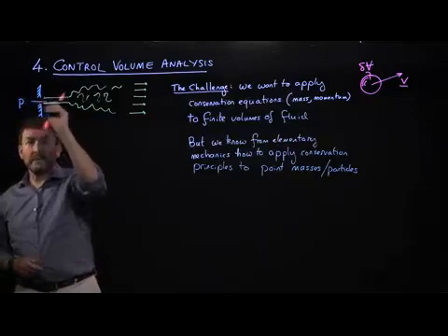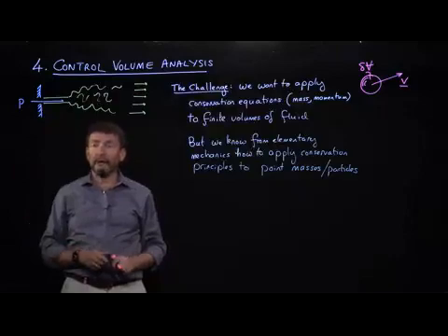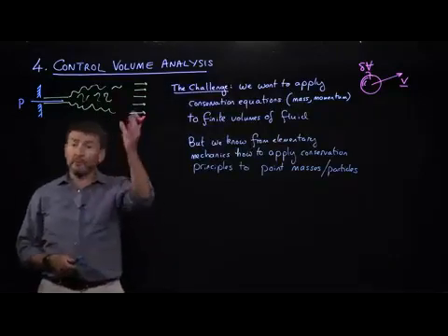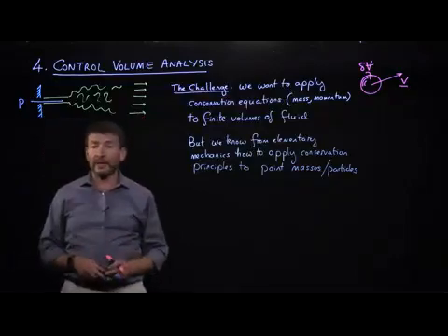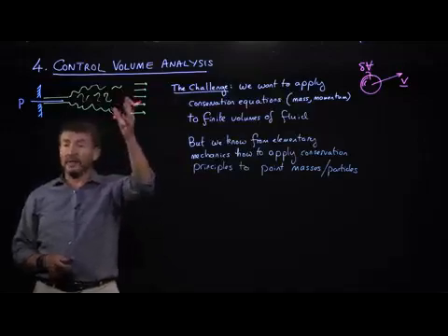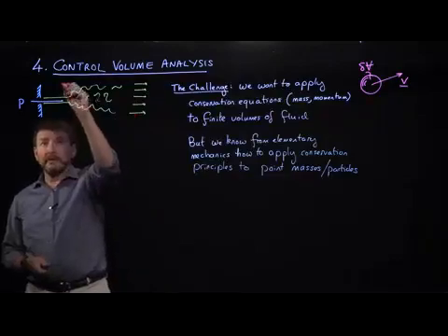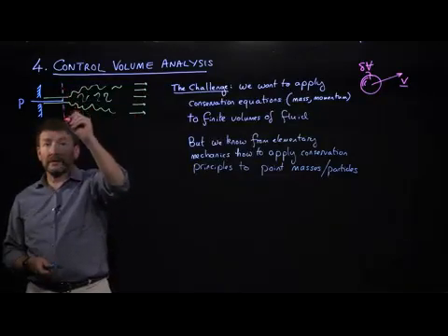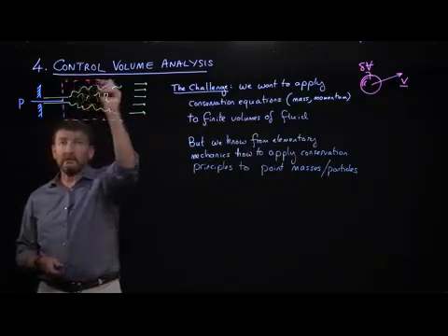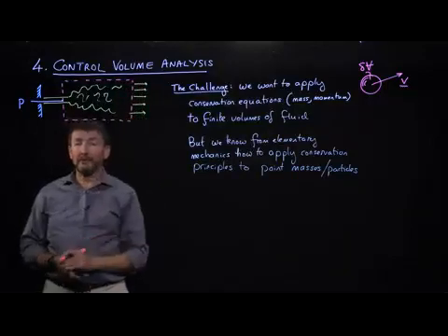We saw that we could apply the Bernoulli equation to think about the idea of straight streamlines coming out and calculate the velocity at which the fluid comes out of this jet. However, we also saw in pictures that very rapidly the jet becomes unstable, becomes much more complicated, and that viscous effects become important here. And we don't really know at the moment how to take into account those. But we could certainly see that there was maybe a possibility of saying, let's not worry about what's going on inside this. Let's draw a boundary around it and just ask what's happening at the boundary.